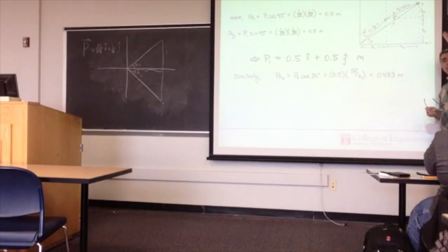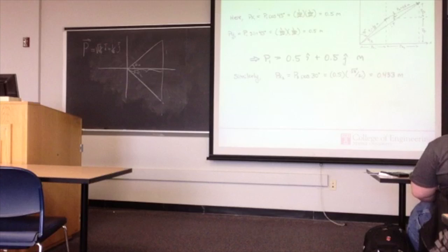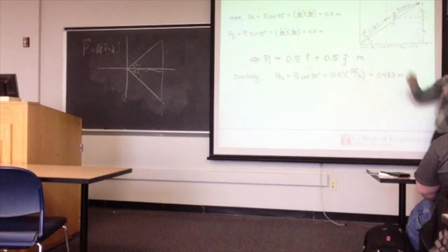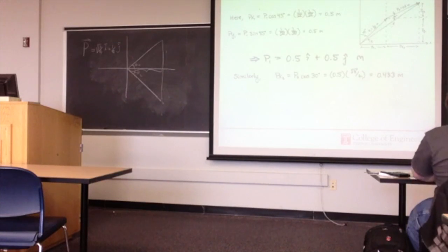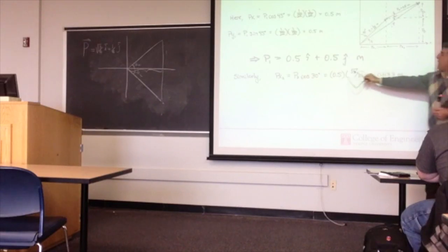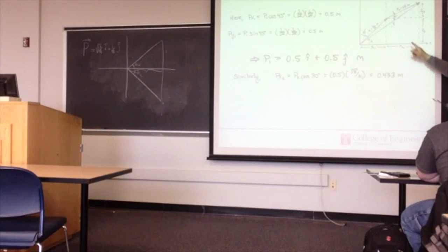Theta 2 was the angle that he made with the arm, and the angle was 15 degrees. So when we subtracted 15 from 45, we got 30 degrees on the elbow down. So what I said was wrong. That's right. So we have the angle cosine of 30 degrees, therefore you should be able to find px2.